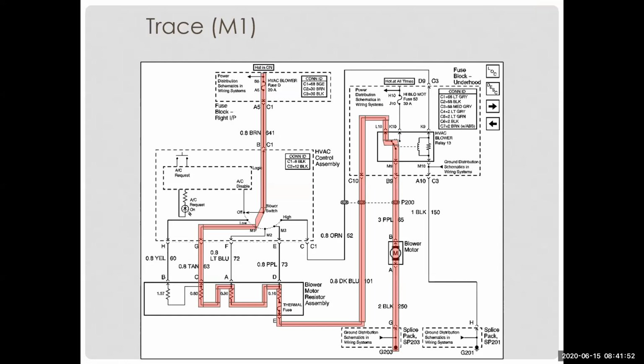12. 12 or system voltage, right? I would have taken either answer in this case. The most correct answer is system voltage because we use system voltage a lot on a car because that changes whether the car is running or not. So if I'm key on, engine off, system voltage might be 12.4 volts. If the car is running, system voltage might be 14 volts. So you're going to hear the term system voltage used a lot.